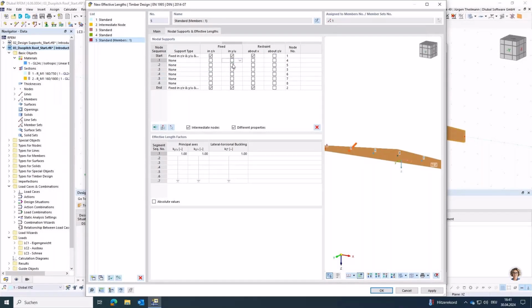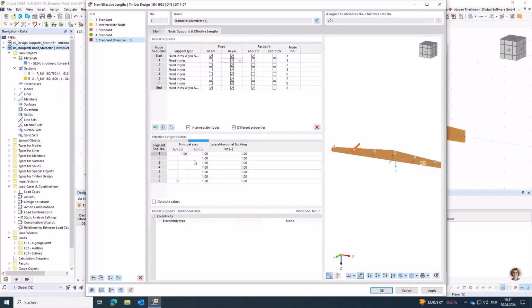And we can simply click on these checks to add the lateral supports, either one by one, or you click the first and the last of those for a multiple selection, then hit on and off as you prefer. And you can see now we have our lateral supports. This directly affects our effective length factor for this.